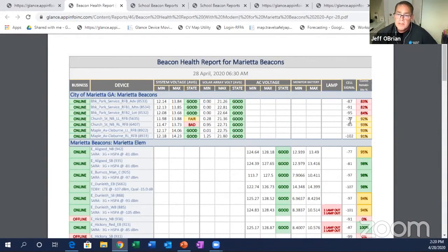What's important about that is that the devices sometimes reacquire a new connection to the cell towers when they're out on the network. That could be because we've detected a poor or weak connection, or for a variety of reasons it just did a reset. It's part of the health aspect of what we're doing to maintain good connectivity to the network. When that gets reset, we'll see these numbers change, and eventually they trickle back into the green section, which is 98 to 100% of cell signal strength.